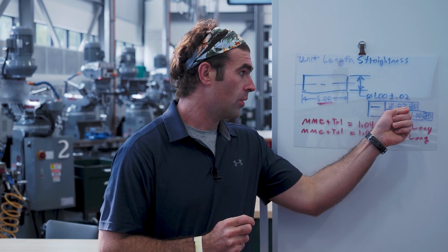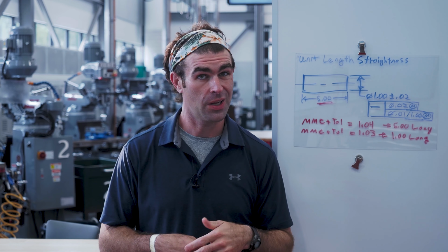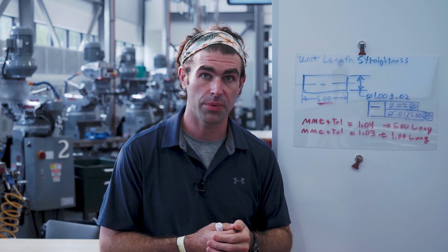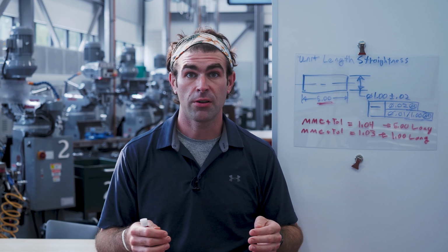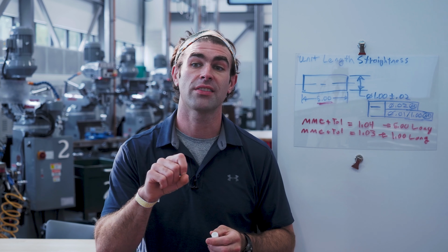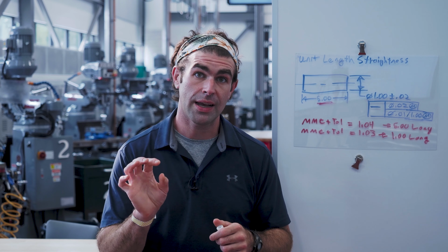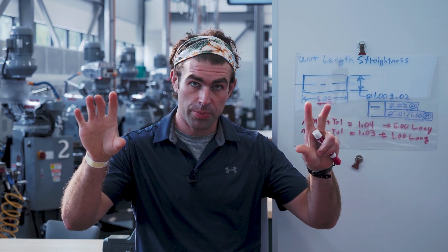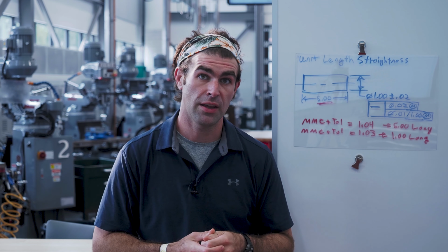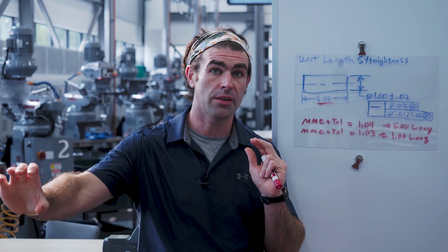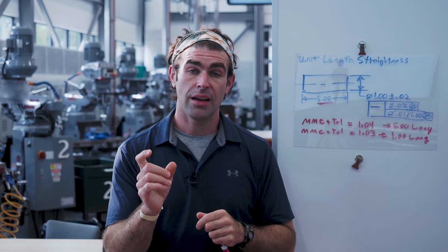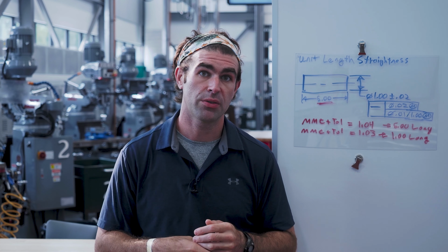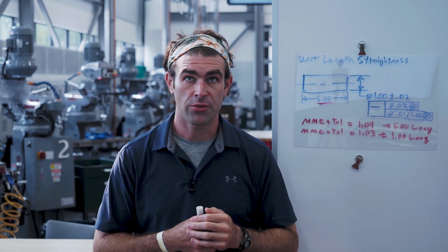Now, in reality, these two tolerances wouldn't be so close to each other. It probably wouldn't make sense. Maybe this one would be 20 thou and this one would be 1 thou or something. But you can imagine if you have a mechanical assembly where you have a collar that has to slide across a shaft, you really need that collar to fit pretty good while it's sliding. But if the shaft has a little bit of banana to it, it would still be able to do its thing. It doesn't have to be that straight through the whole thing. It only has to be straight enough to fit the collar at any one place at any given time. Okay, so that's straightness, specifying straightness per unit length.